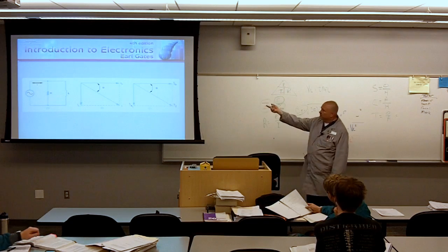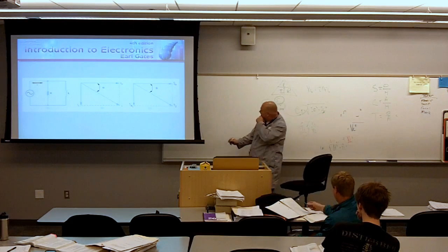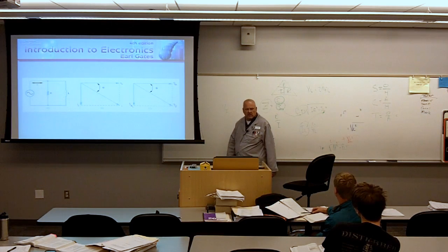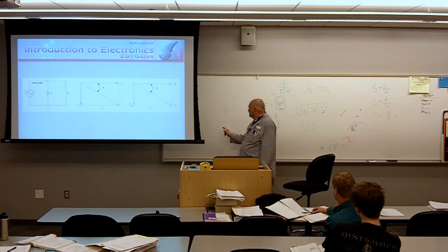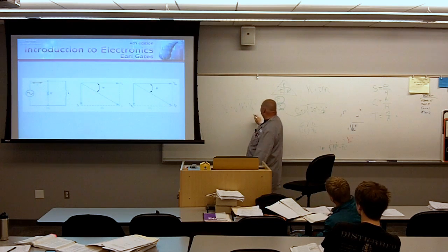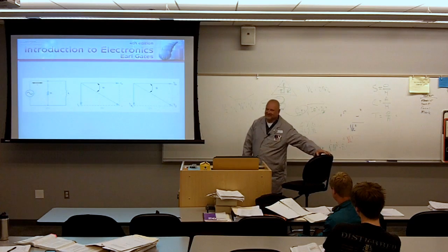It's a heck of a lot easier than the reciprocal of the reactance. IT is the vectorial sum. Absolutely, it has to be for this kind of circuit. So this would be like IZ is equal to the square root of 1 over R squared plus 1 over X sub L squared. Don't. It's a lot of keys you got to hit for a simple question.